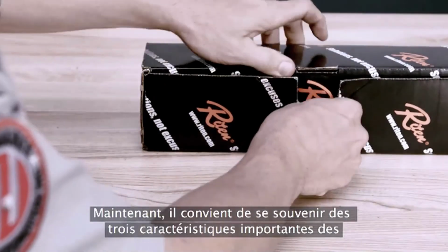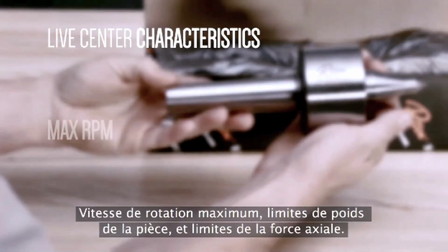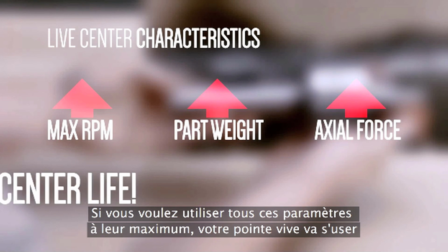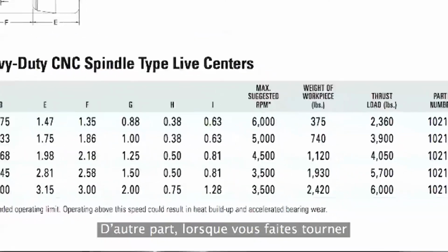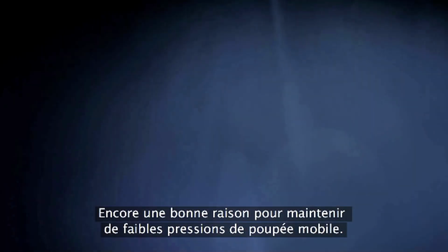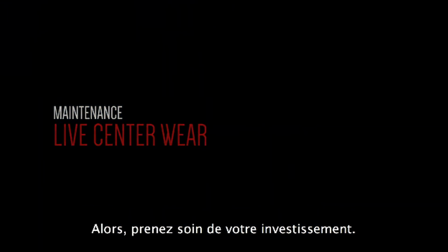Now, live centers have three main characteristics that you need to keep in mind when setting up your job: maximum RPM, part weight limits, and axial force limits. If you were to max all of these out, your live center would wear down and last a fraction of its normal life. On the other hand, when you run your live center at moderate RPM and weight loads, tailstock force becomes the main factor in live center life. Yet another reason to keep your tailstock pressures low. Live centers do wear out, especially if they are mistreated or abused, so take good care of your investment.